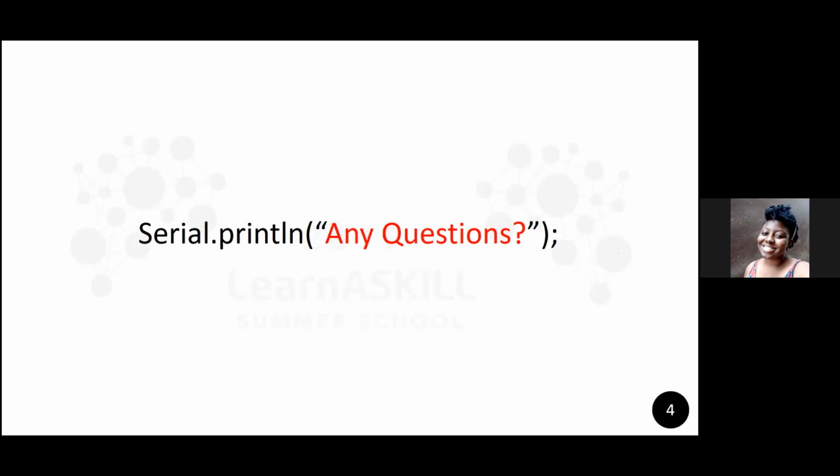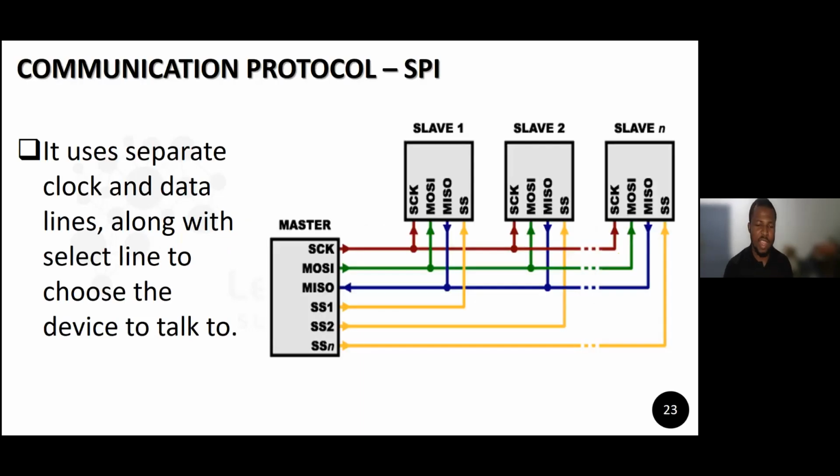Among all these three communication protocols, is there one that you can do wirelessly, or do all of them require USB connections? Okay, so all these protocols are actually wired connections. They are not wireless. Wireless is another thing altogether. For wireless communication, you always need another form of interface like ZigBee or a Wi-Fi protocol, right? But these communication protocols that we are talking about are wired, so they need to be physically connected with cables. Yeah. Okay, thank you very much, bro.